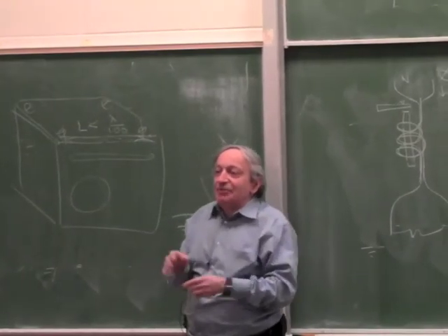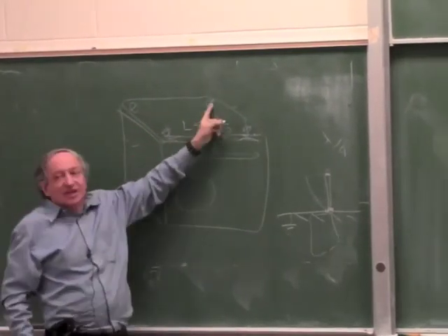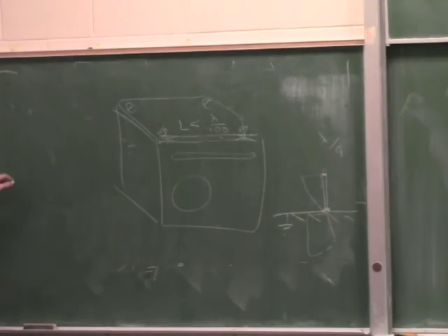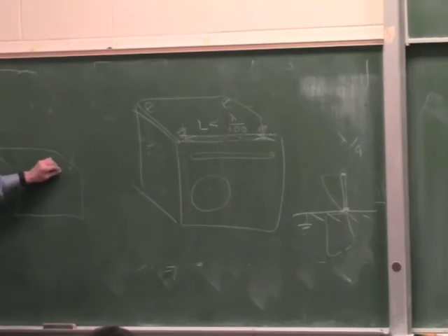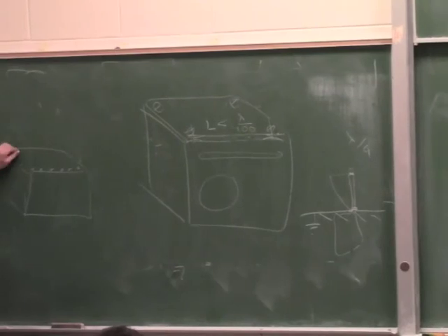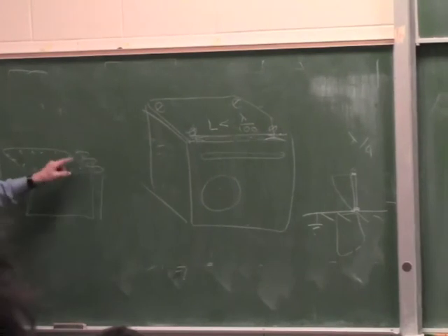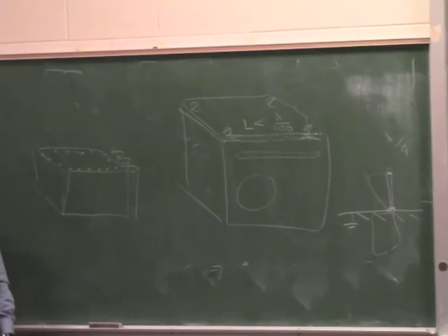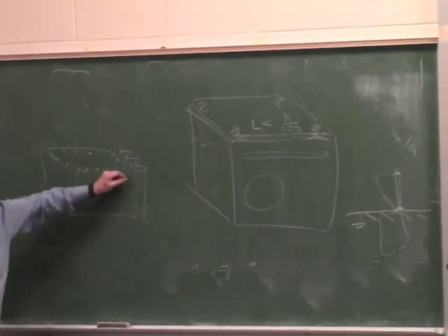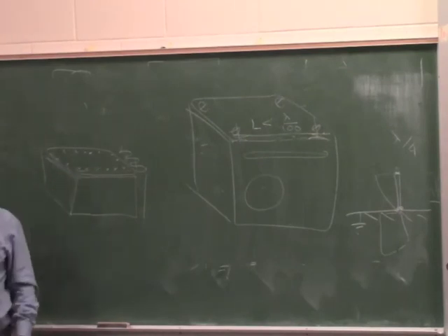And this is the reason when you look at an audio amplifier, it looks like this. It has maybe 4 screws on the cover, but if you ever look at an RF amplifier, because you can buy modular RF amplifiers, okay, they have maybe 50 screws. They have a whole bunch of screws all around the cover, and they have no ventilation slots. They may have fins, like a heat sink, but they have no slots for ventilation. Because everything has to be solid metal, and the cover has to be held down with many, many screws, so there are no gaps. And actually there's even a gasket underneath which conducts electricity. So even between the screws, there is full electrical connectivity.